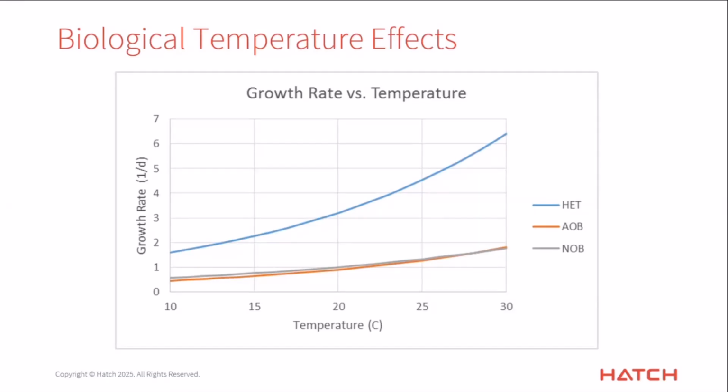It's a function of many other things, such as what your DO is and the SRT, and the sensitivity of these two biomass types to oxygen and so on. But I will mention it. It is sort of a feature of the way that these things have been calibrated over time. I have actually worked on projects where nitrite accumulation was the whole point of what we were trying to do with the modeling, and this effect is there in order to be able to predict that when it is relevant.